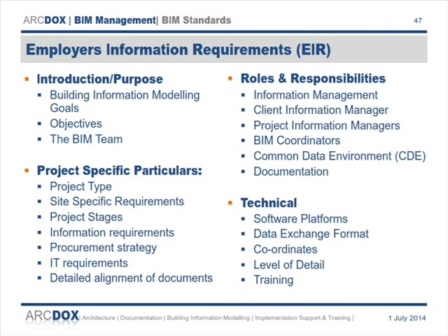Are we using BIM just for on-site coordination? Are we going to use it for off-site fabrication? Are we going to use it for FM or not? If you're not using for FM, then you can put a lot less information in the model. So you need to define what the overall goals are. Why are we using BIM and what do we want to get out of this process?